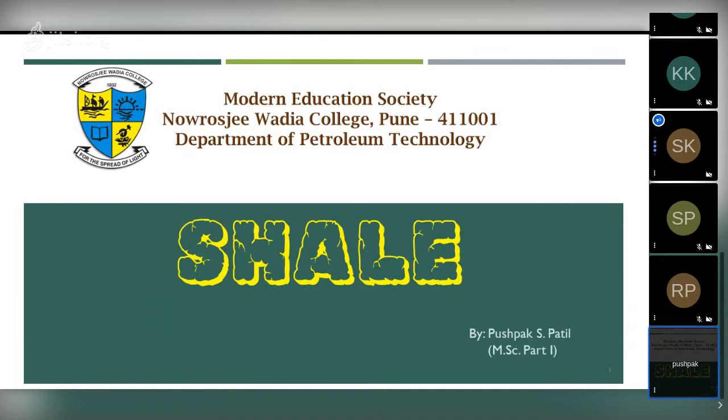There is a certain place where we have to place the unit, and there are zones. For a mud logging unit, it has to be in zone B or zone C. The rig is categorized into zone A, zone B, zone C. It depends on your unit, how it is manufactured, as units have ratings. A few units you can put in a zone, a few units you cannot, because it is an explosive area, with gas on the rig floor, and it should be 100% sealed. So those are the A zone units.